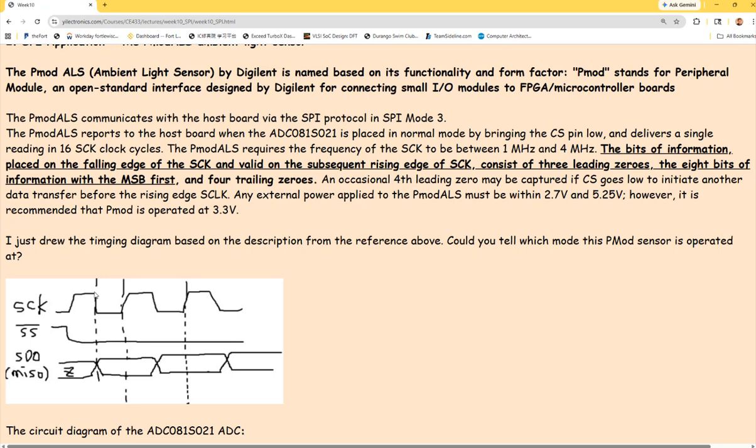So the previous falling edge update will place the data here, it makes it available, so data starts coming in. And the subsequent rising edge will sample it right in the middle of the data. So you should draw it, so this should happen this way. And then until the next falling edge, it updates the data, places the new data here, and then the subsequent rising edge will sample it. So just keep going like this. However, it has to be enabled before that, right? So that is why the previous rising edge will enable it. Okay? The rising edge enables it.